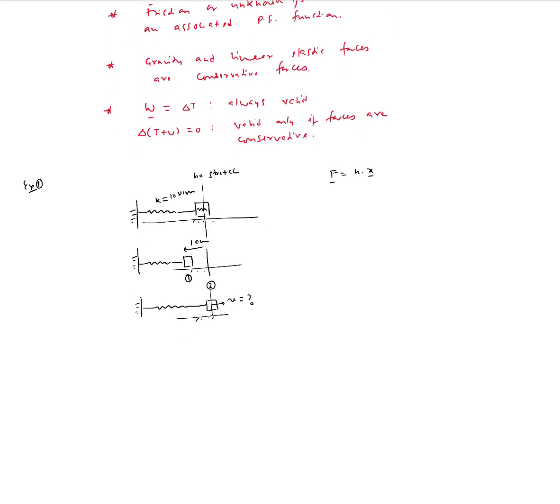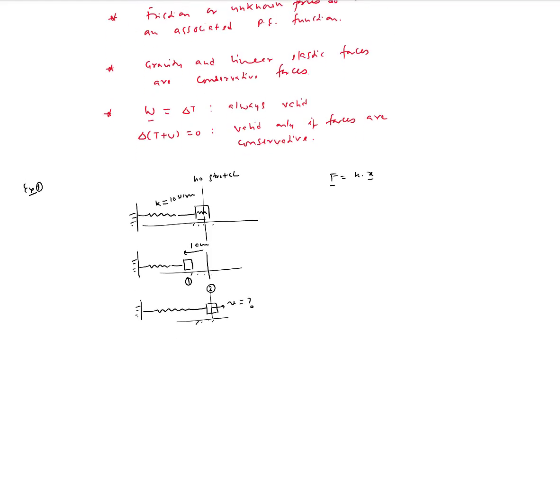To solve these kinds of problems, the first thing you have to do is apply a systematic way of looking at whether this problem can be solved using the work energy approach or not. So let me first give you a process for solving this problem, or we'll call it procedure. The procedure starts with a test. The test is that you have a finite displacement scenario, and you have to relate velocities with displacement.